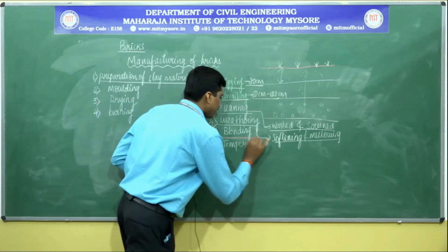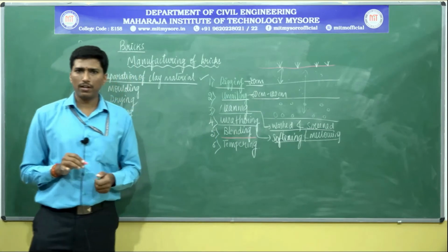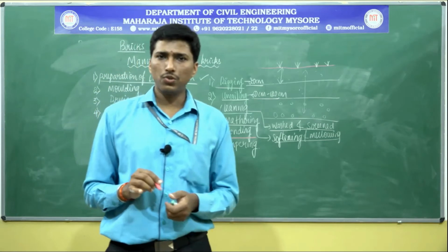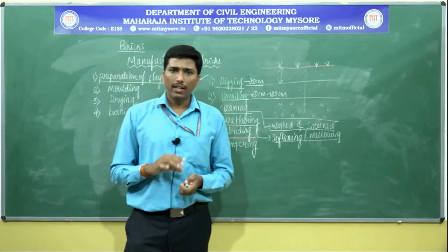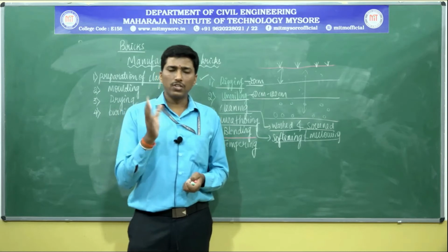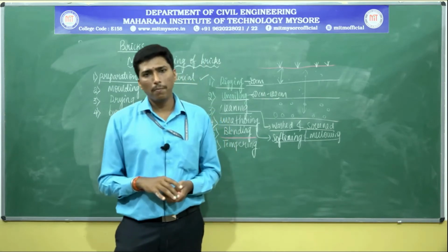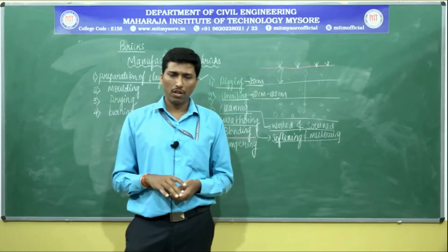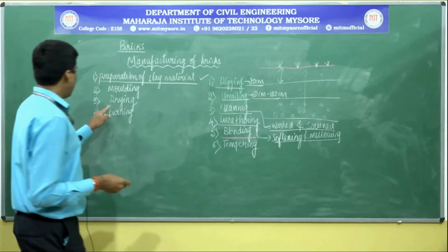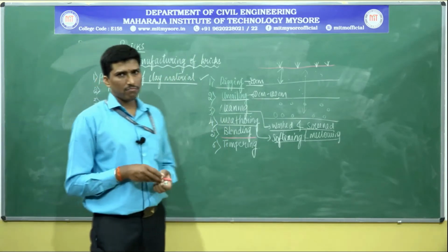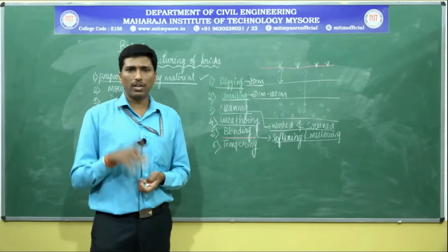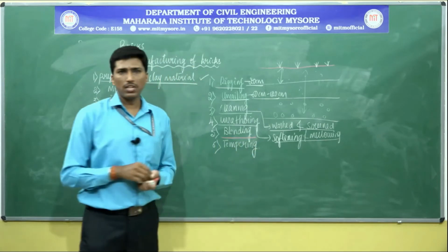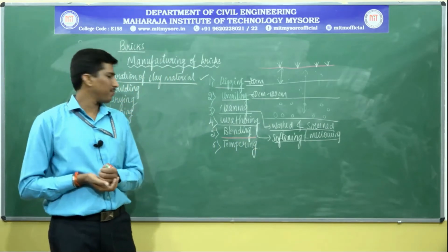Blending. Next step is, what is meant by blending phenomena? Blending, it refers to mixing of the materials to make the ingredients of the material as a homogeneous or uniform mixture. What is the reason if it is not in uniform? The output of the burnt product or during the drying, the cracks will tend to develop. That should not tend to happen. For that particular usages, a blending is necessary, that is a proper mixing phenomenon.